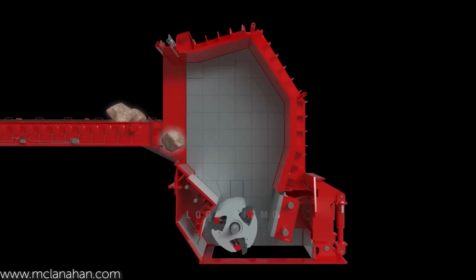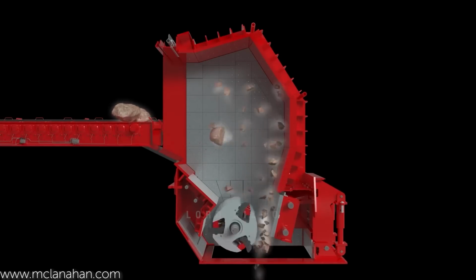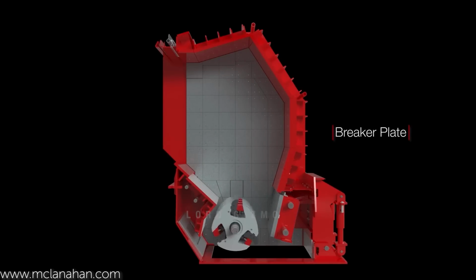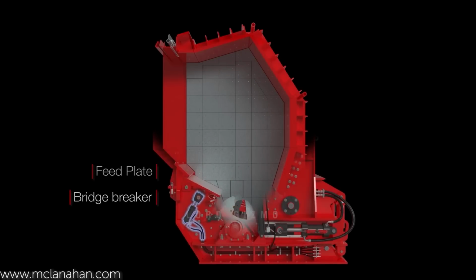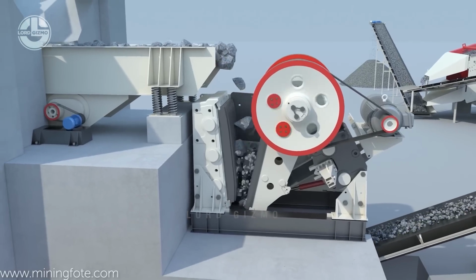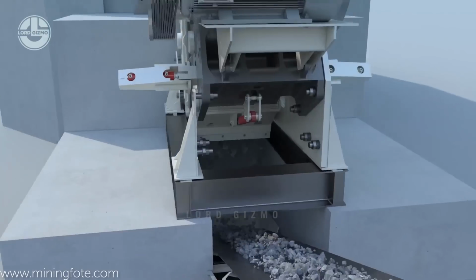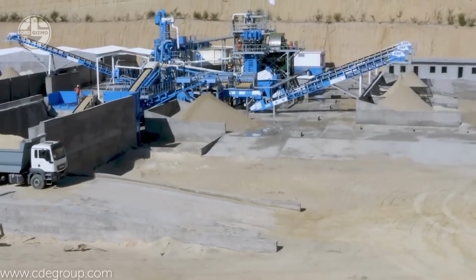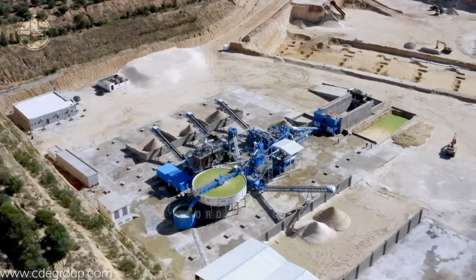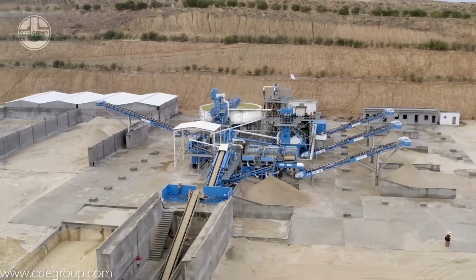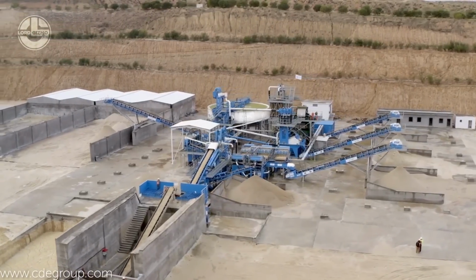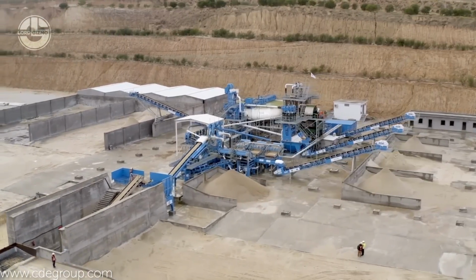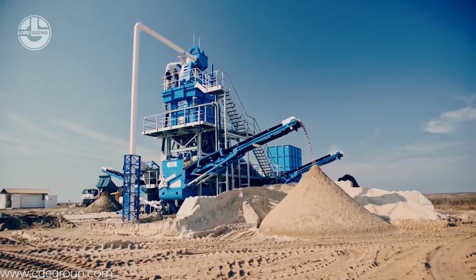Likewise, sandstone falls on the high-speed rotor drum in the impact crusher, which breaks upon impact. The material then encounters a series of anvils or curtains that further crush it as it travels through the crusher. The crushed sand is still not pure silica. It needs to be graded and purified. For this purpose, CDE Group, a renowned company that manufactures wet processing solutions, has designed this silica sand wash plant, which can produce 220 tons of glass sand every hour.